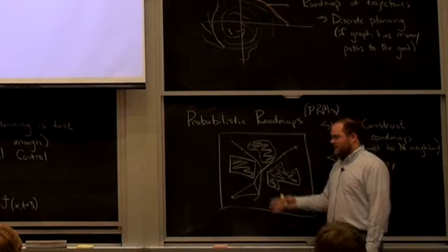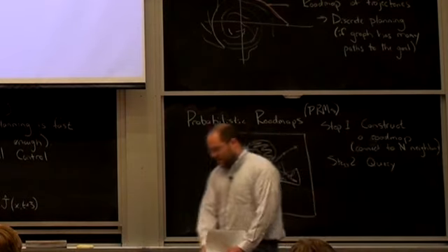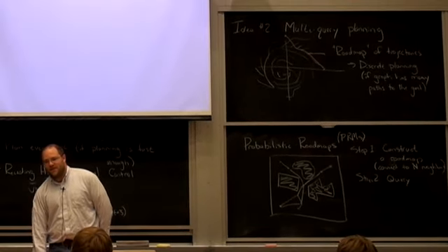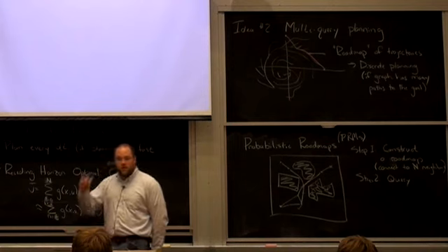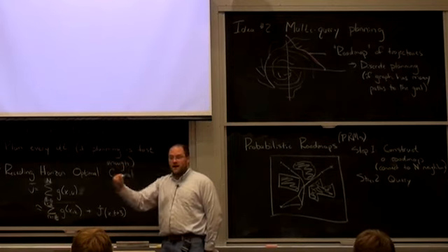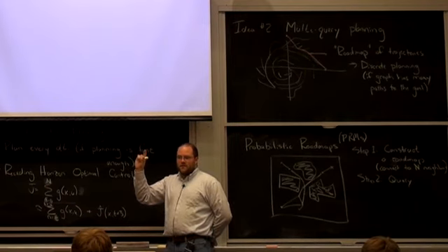Maybe my open loop trajectory optimizer told me to walk along the side of a cliff, right? And wasn't really paying attention to the fact that stabilizing that's hard, right? Or maybe it was saturating my actuators the entire time. That's a very real possibility. And left me no margin of control to go back and stabilize it.